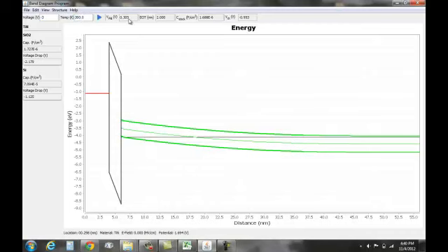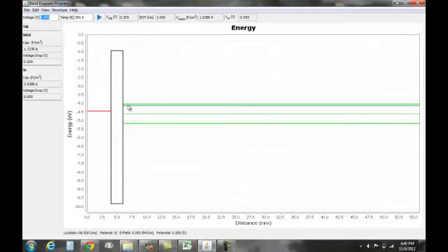These other parameters are relative to the structure itself, the device itself. So the flat band voltage remains the same. EOT, the effective oxide thickness, remains the same. The capacitance of the entire stack remains the same, and the threshold voltage remains the same. These parameters are provided once given the structure of the material of the device. Certainly, I can copy these numbers with Control C, place the flat band voltage in the voltage field, and enter it, and notice that all the bands are flat.